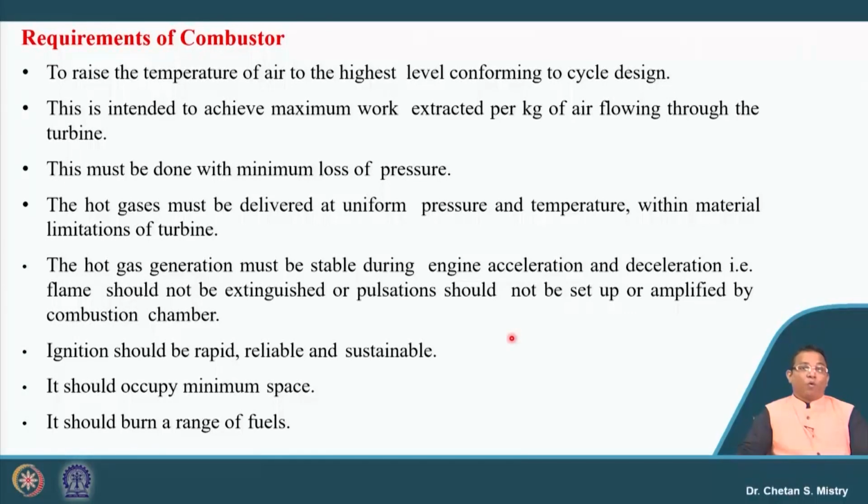Now, what are the requirements for the combustor? Very first, it is used to raise the temperature of air to the highest level as per the requirement of my cycle. We must understand the maximum cycle temperature is nothing but the exit from my combustion chamber.